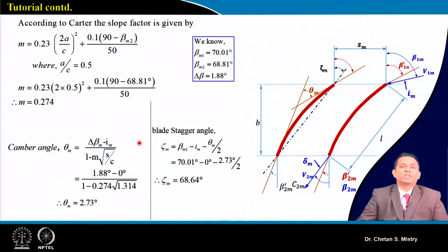Now once we have decided with that, this fan we are talking about is a low pressure fan, and we are not expecting it to be expensive, and we are not looking at running that fan in a variable speed configuration. Maybe rarely; it will be rotating at a constant speed. And that's the reason, if you look carefully, this blade we are making will be made by bending of the plate. This is what the blade will look like. It is not having an aerofoil shape.